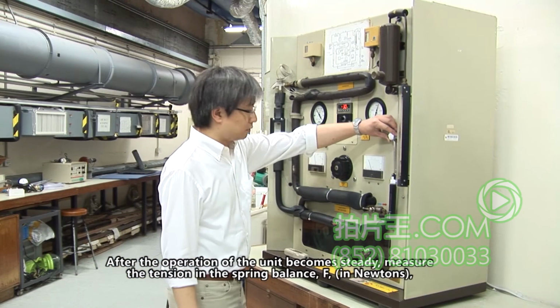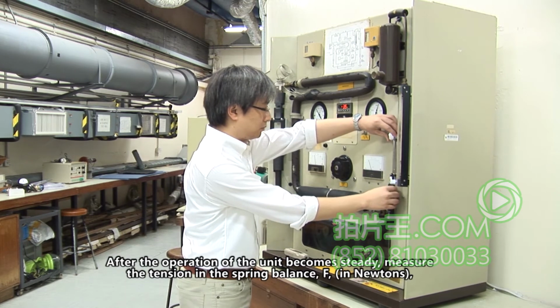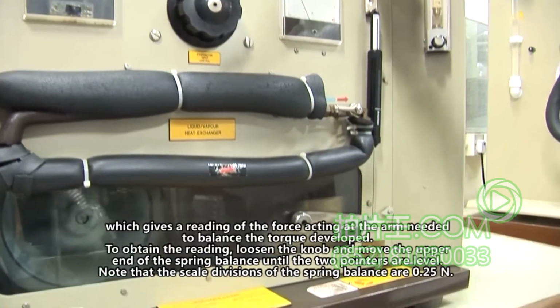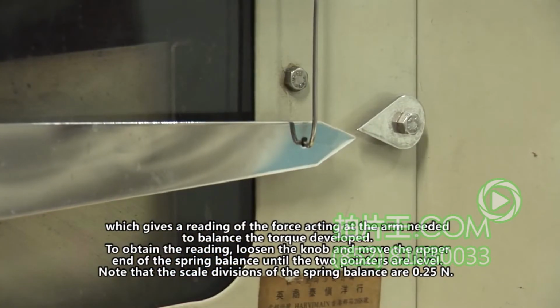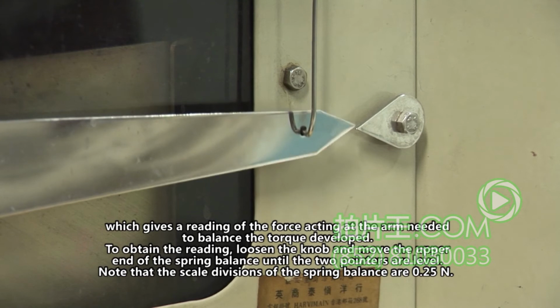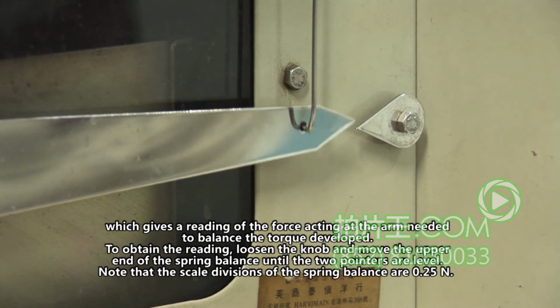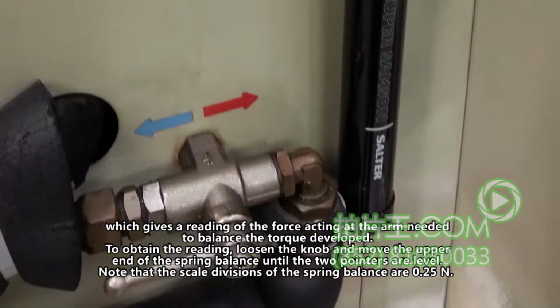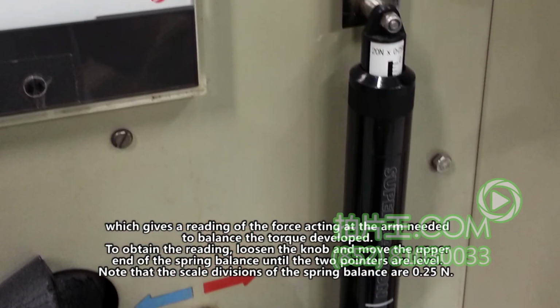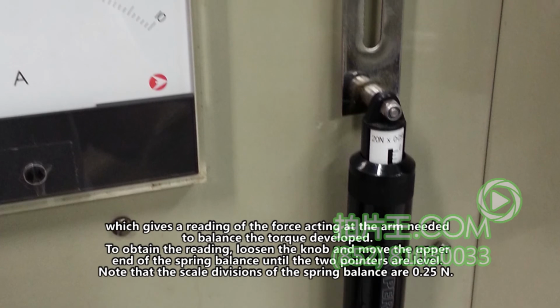After the operation of the unit becomes steady, measure the tension in the spring balance, F in newtons, which gives a reading of the force acting at the arm needed to balance the torque developed. To obtain the reading, loosen the knob and move the upper end of the spring balance until the 2 pointers are level. Note that the scale divisions of the spring balance are 0.25 newtons.